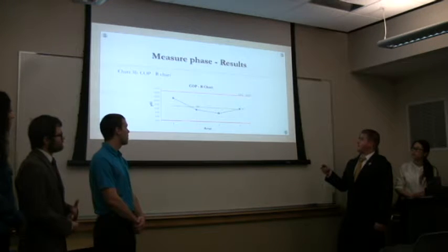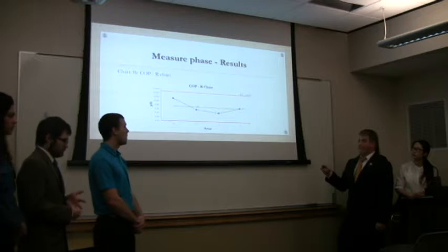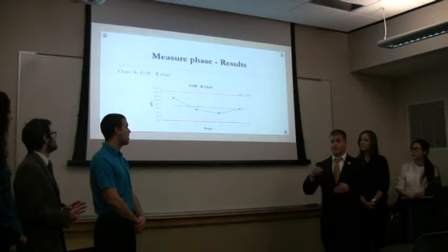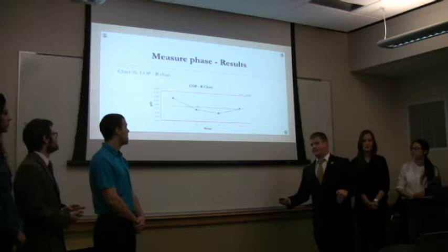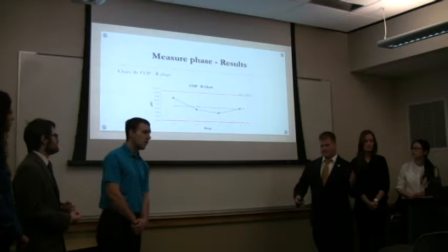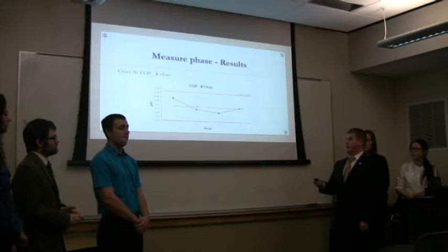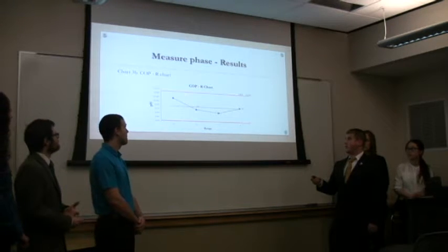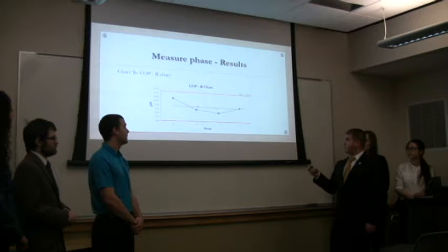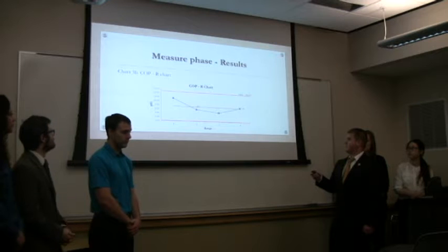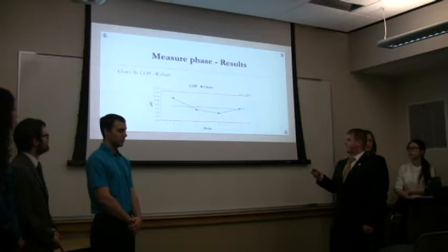As you can see, the range is now about a 15, which is a pretty large range between all of our samples. Now, we didn't collect as many samples, so it's possible that we had too clumped of data, and so outliers moved our limits around a little bit too much. But fortunately, our average range was only about 7, and they popped around a little bit.